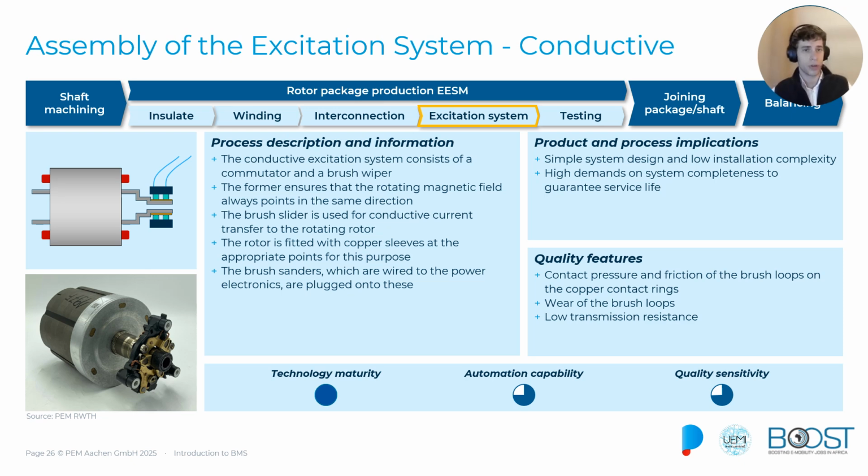But most of the time we see a conductive excitation system where the rotor is energized via direct electrical contact by the use of brushes.